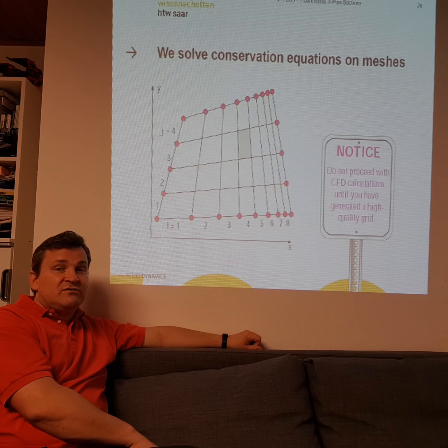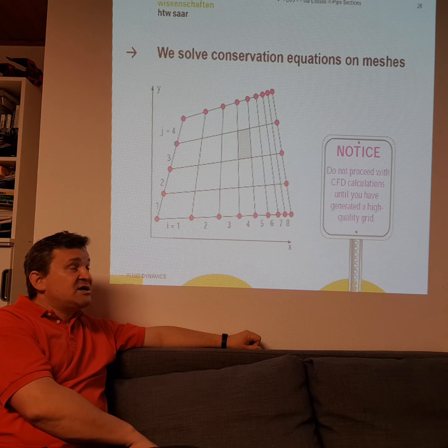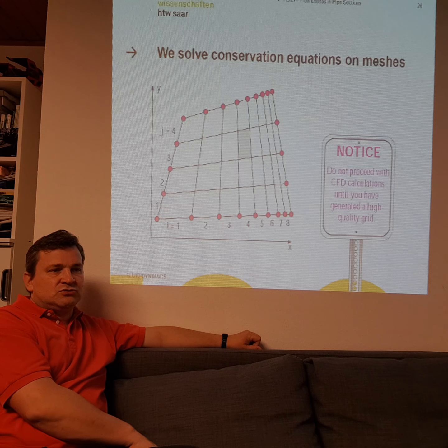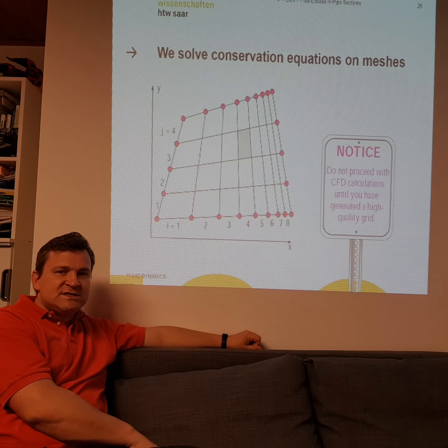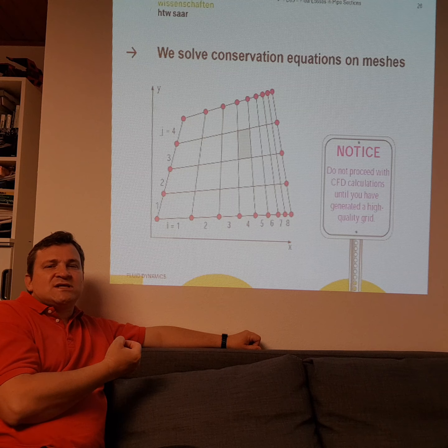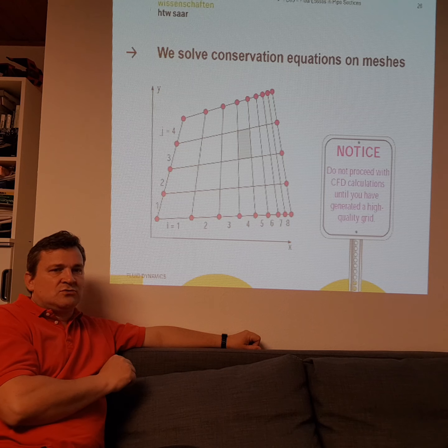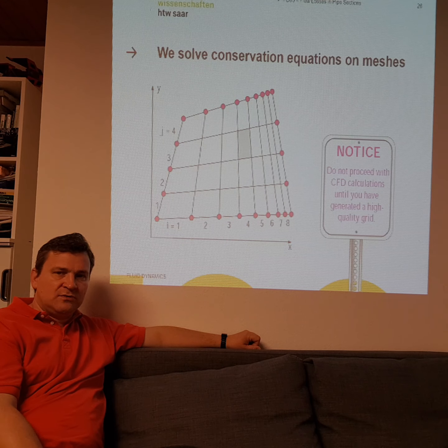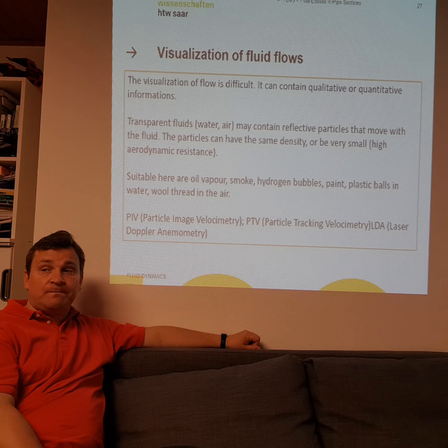Of course, if you have a rough pipe and the mesh is too coarse for this roughness, or too coarse to build up a realistic mesh for the armature or for the valve, the results will also not be so realistic. So always keep this in mind.